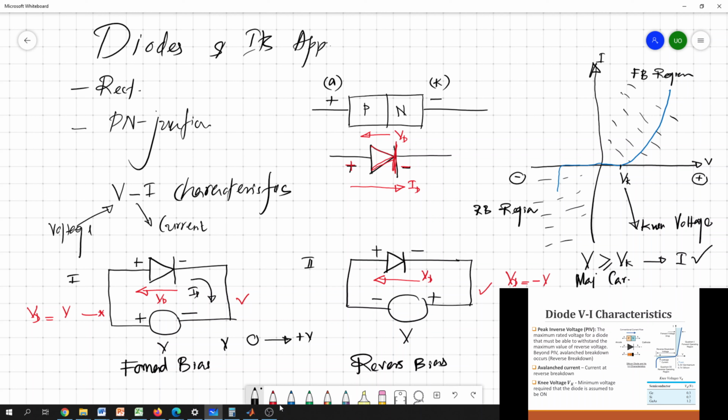But once you apply a negative voltage across the PN junction of this diode, the current is very small. If you apply a voltage less than 0, you basically can't see a current, but you can see a current in the microampere range. In the forward case it's a milliampere range, while in this case the current is in the microampere range.